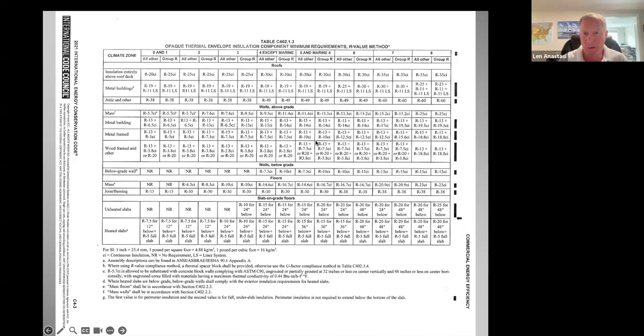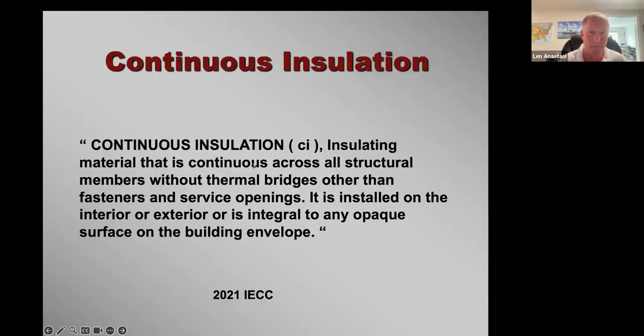And if you do this in a building with medium or high interior relative humidity, you're going to hit the failure criteria for WFI for RH values within the wall. So I don't like using this. I like to put all my insulation to the outside of the sheathing and then go by the performance requirements rather than prescriptive requirements.